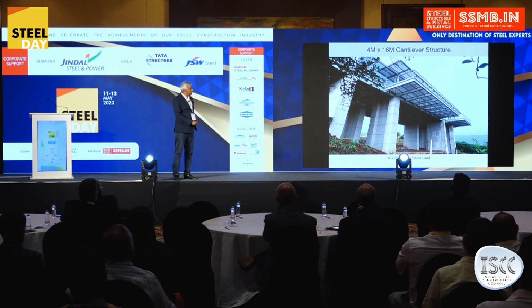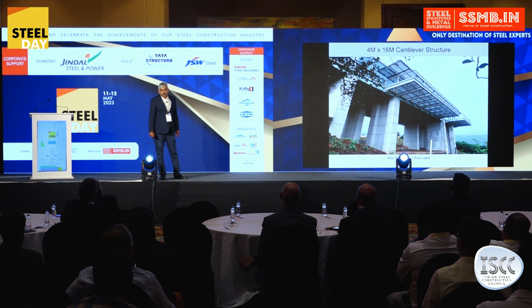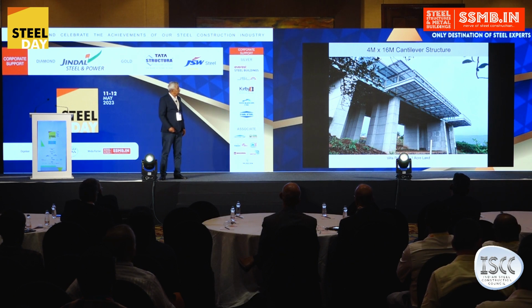You can see the columns are around 9 meters high, with 4 meters projected by 16 meters. The grating is made of 1.5 mm carbon steel. They are formed and punched, and are available in 4 meter by half a meter. Similar gratings are put on top for the rain beating down.